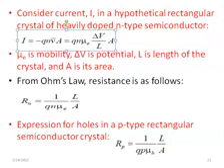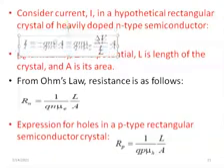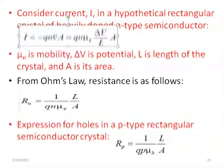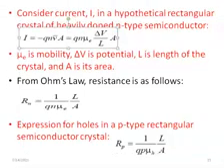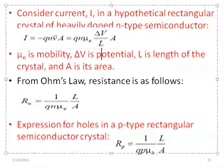Q is the charge of the electron, n is the concentration of electrons, V is the drift velocity we talked about, and A is the cross-sectional area of that rectangular crystal. You can remove this V and replace it with this. Instead of putting V, we put mu E dV/dL, and our rectangular area is still there.